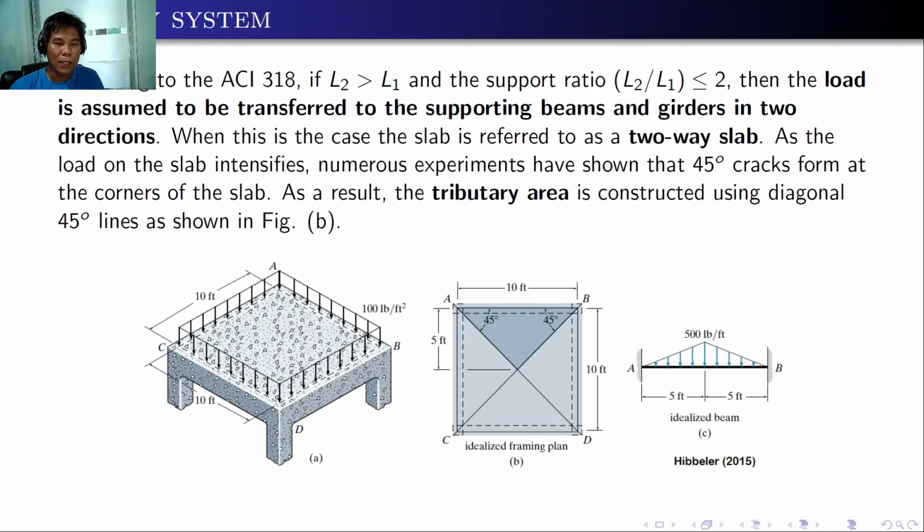As the load on the slab intensifies, experiments have shown that 45 degree cracks form at the corner of the slab, assuming that we have a perpendicular beam. So the result will be 45 degrees.